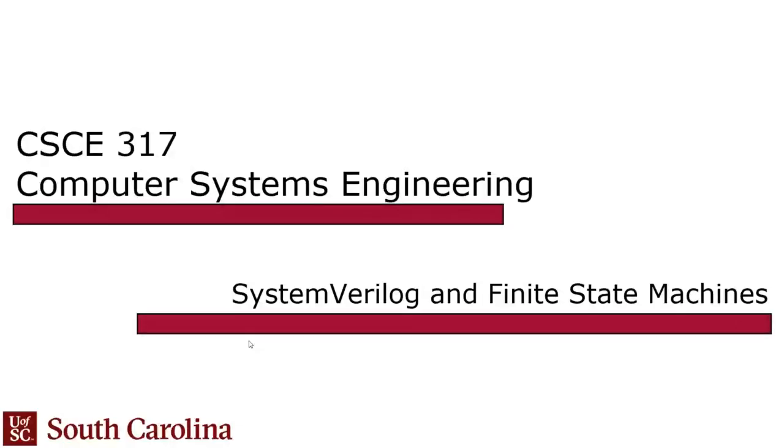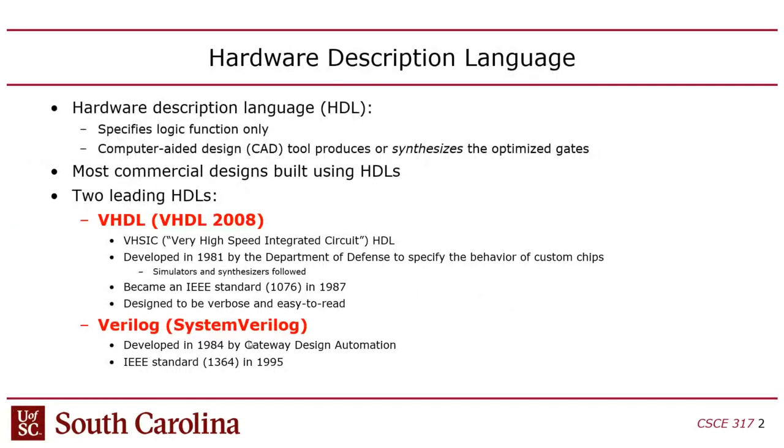so there's a lot of advantages, but there are also disadvantages. The disadvantage is you can design some HDL code and it may work perfectly in a simulator, but when you go to generate hardware, which is a process called synthesis, as opposed to compile, it's not called compiling, it's called synthesizing. When you synthesize the hardware, you find out all of a sudden that you have a long path, right? Path being you've got a lot of logic gates in series with a lot of wires. Why a lot of wires? Because you've got a fan out. You've got a lot of fan out in your code, and that fan out has a lot of capacitance, and your design is slow.